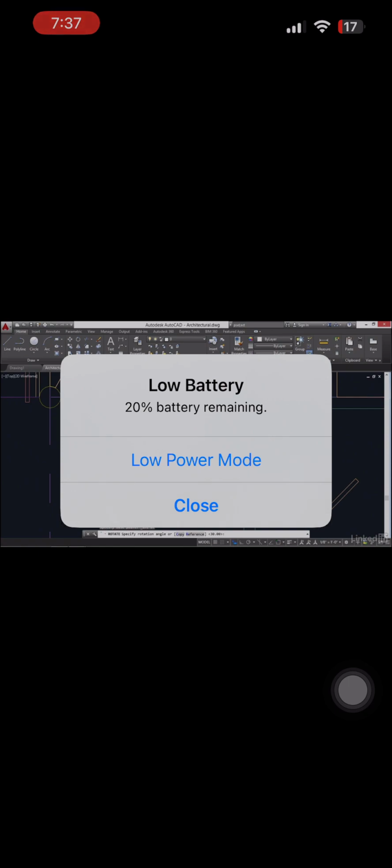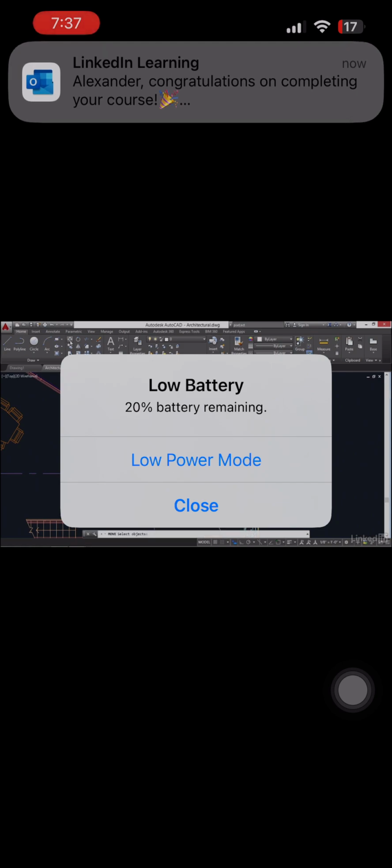So again, hold down Shift, right-click, choose End Point, and snap here to the end point of that line. Now the chair is rotated perfectly aligned with this step. I can then move it up into the room like so.